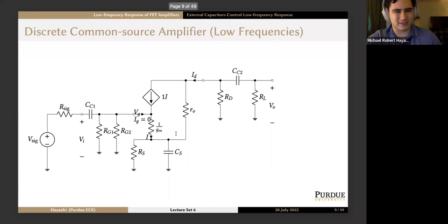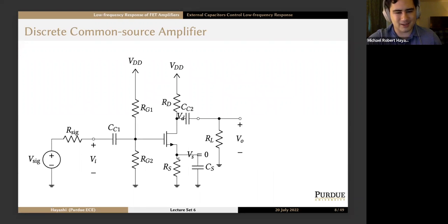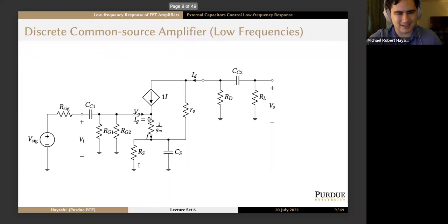And then we'll use the equivalent T model. So we'll have our current source here, where the control current you have to label is right here, with 1 over GM as a resistance in our small signal model. We also have the output resistance right here between drain and source. Our source has RS going to ground and CS going to ground.